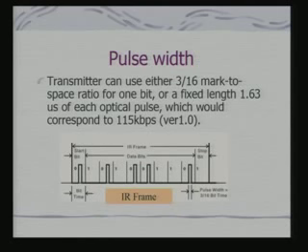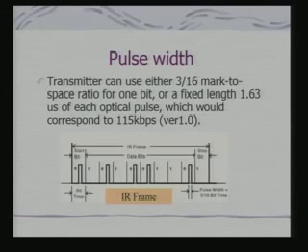So what is really asynchronous transmission? If we look at a UART, we have seen that almost all the devices, all the microcontrollers, have a UART interface. Typically UART supports asynchronous transmission, and in an asynchronous transmission, typically the clock is not part of the data. You have a start bit which indicates the beginning of the data, and a stop bit which indicates the end of the data.